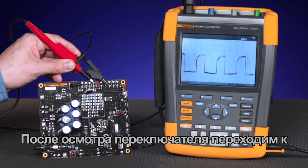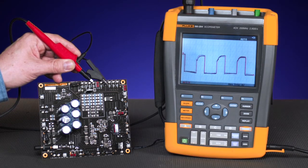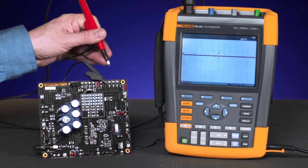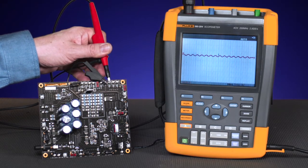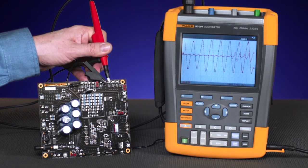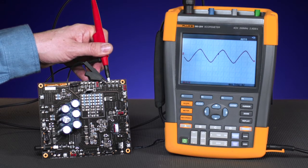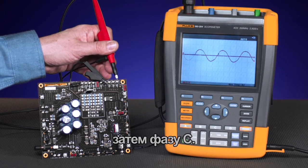After inspecting the switch, we can move to the three-phase output signals, looking at the sine wave for any distortion. Looking at phase A, to phase B, and then to phase C.